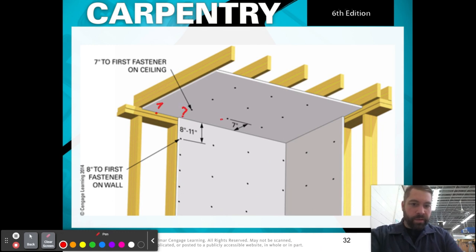None. The first one that we're putting is about 7 inches off because this panel, we're taking and putting it right up against that one, and it's kind of acting as a fastener. So it's helping take that load from this little bit and transferring it to this sheet. And then because we're doing that, we're going to go about 8 inches to our first fastener, right? So we don't need to put them up here either.